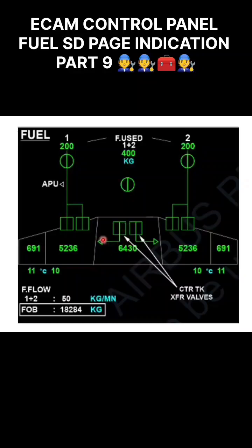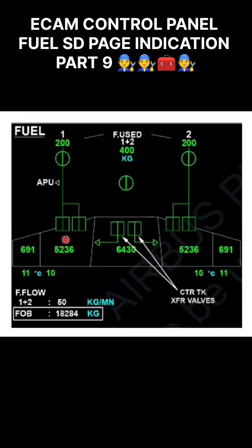If it is commanded close, it means there is some fuel limitation in the wing. There is a fuel low level, then high level, then underflow level, like this concept. We will discuss the wing in 8828 fuel, but here we will just take an example. If fuel goes below 500 kg, under the low level sensor, then this transfer valve will automatically open and keep on supplying. Once the wing fuel tank is full, then again it will be in the off condition.